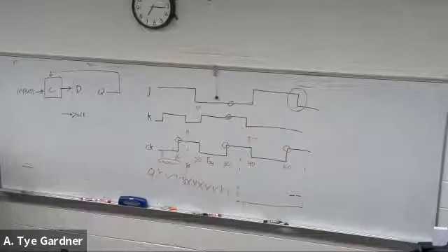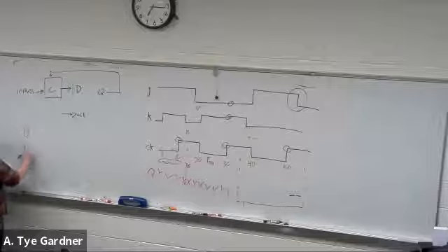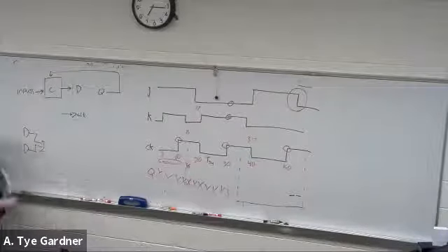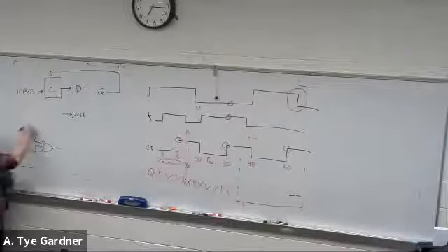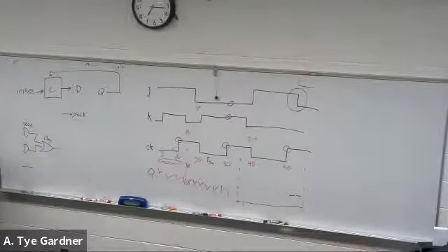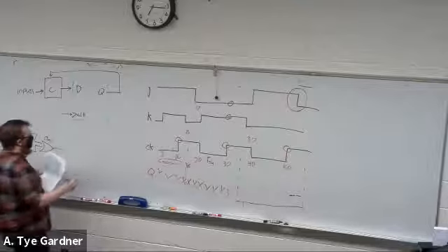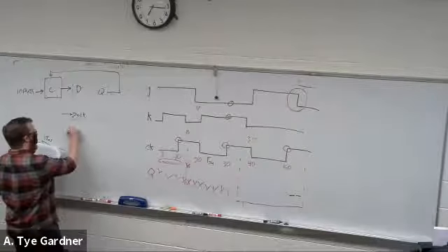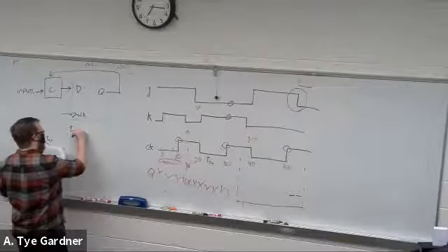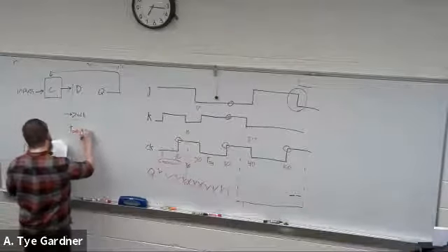and the combinational circuits. So when I say combinational circuits, I mean it's going to be like a sum of products expression or something, right? And it's going to be like 10 nanosecond delay here and a 13 nanosecond delay here or something, right? And the question is, how fast can I go? Well, we have this nice little expression that says, well, let me just write this down rather than trying to talk.